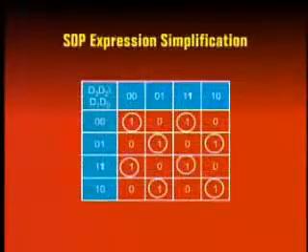The information in the function table is mapped directly to a 4-variable Karnaugh map to simplify the Boolean expression represented by the odd parity generator function. None of the ones mapped in the Karnaugh map are adjacent to each other, thus the function mapped to the Karnaugh map cannot be simplified. However, using the rules of Boolean algebra, applying De Morgan's theorem, and knowing the function table of exclusive OR and exclusive NOR gates, the Boolean expression can be simplified.